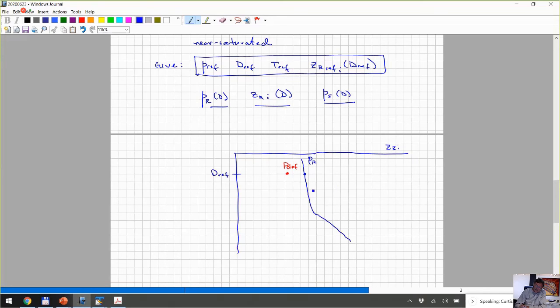When you get the composition, you can calculate the saturation pressure. That dew point will vary because the fluid is becoming richer, and it will go down here. Then when that dew point intersects the reservoir pressure here, it flips from being a gas to being an oil. And the oil composition that it finds below the contact will have a bubble point that decreases with depth.